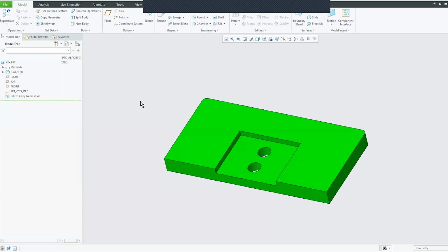See one more on the chat. Can you move the line once you've used it to mirror? Yes. Yeah, you can lock it, you can unlock it, you can drive it by a dimension if you wanted to, anything like that. And remember, if it's not locked, if you move it, then the things that were mirrored about that line are going to move as well.